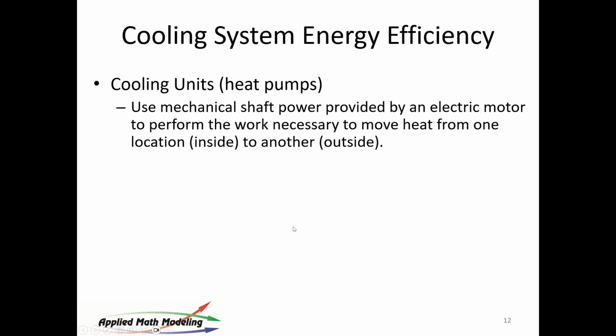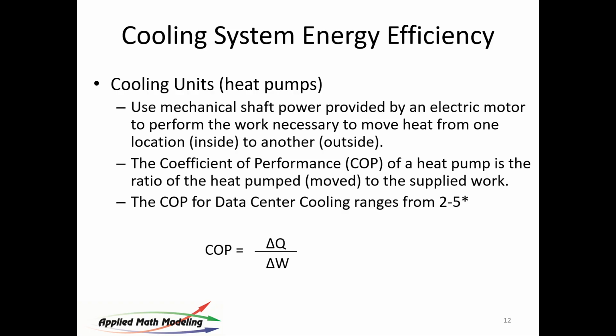Remember that cooling units are really heat pumps. That's what they are. They're pumping the heat outside. A heat pump uses shaft power to provide the movement of energy from one location inside to another location outside. It's a pump. It pumps heat. And the coefficient of performance of the heat pump is the ratio of the heat moved compared to the work supplied.